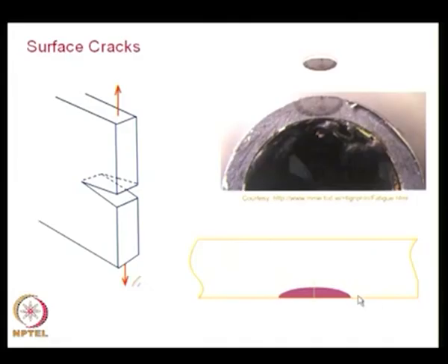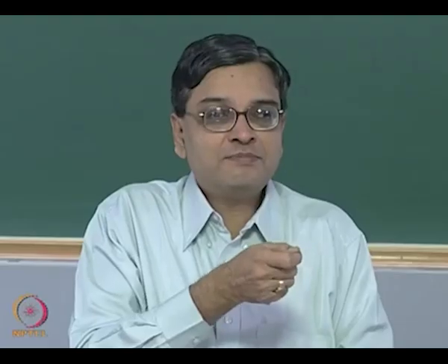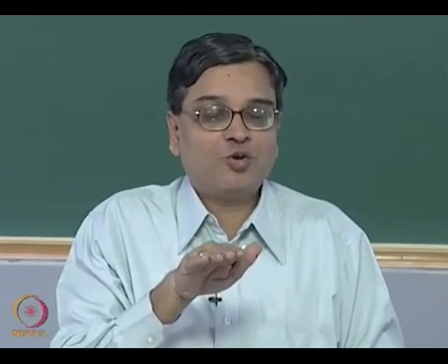So if you have a scratch, when you are concentrating on the tip of the major axis, there is no depth on that side, it is as good as a simple scratch. In fact, if cracks did not extend in that direction, then even scratches would become very dangerous. When you have a scratch, because of corrosion products, the crack penetrates into the material. So you have to look at what is the crack front. See, that is very important.